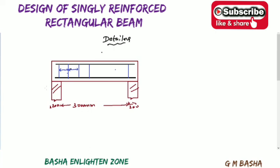We found the spacing for the stirrups of 6 mm bars. We are using 6 mm diameter bars at a spacing of 120 mm. Here two hanger bars of 10 mm dia, and this one will be 3 bars of 12 diameter.